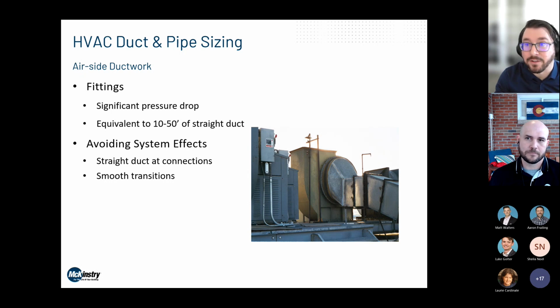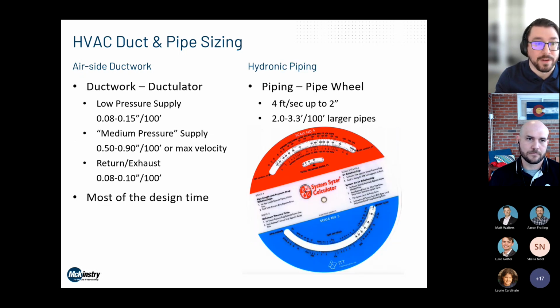Medium pressure would be half an inch to 0.75 inches per 100 foot. That's going to generate more noise. That's how that manifests. Pressure goes away, it makes noise and heat, but noise is what you're going to experience mostly. There are different kinds of noise too, but that's the one that we're going to probably deal with most directly with HVAC systems.